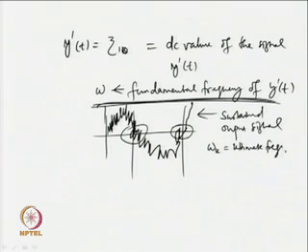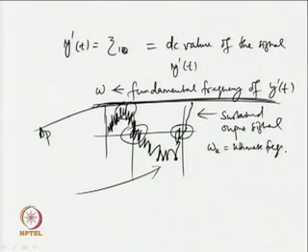Similarly, what about the peak amplitude of this signal? You see which can qualify as the peak. I may get an erroneous value if I measure this value. Similarly, I can have multiple peaks. Look at the signal here: how many negative peaks you have? This can qualify as one negative peak, this can qualify as another, and so can this one. So, we have multiple measurements, then which one to choose? Certainly this is going to give us an erroneous peak amplitude.